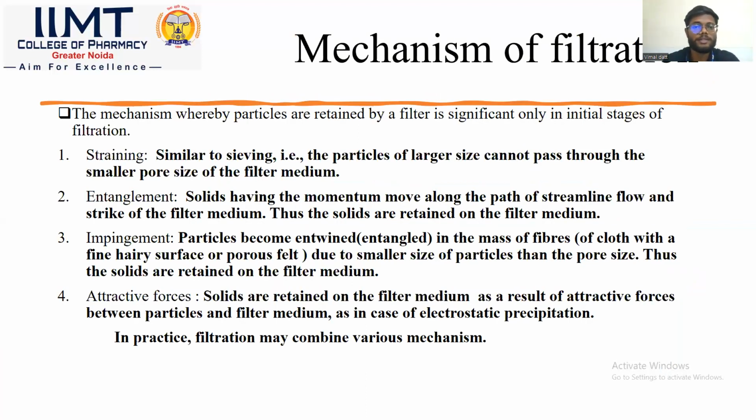The mechanism whereby particles are retained by a filter is significant only in the initial stages of filtration. First point is straining. Similar to sieving, the particles of larger size cannot pass through the smaller pore size of the filter medium. Second is entanglement.